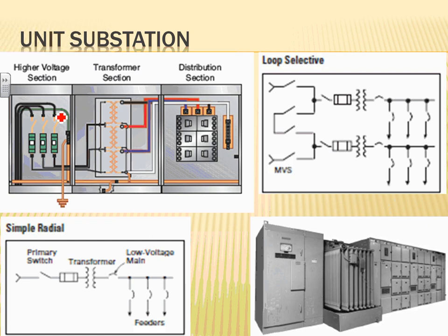Unit substation, I thought I'd just show you a lineup of a unit substation. We use these a lot. So here's your 13.8 coming in here. This is, let's just say, 2.5 MVA, and from this side will typically be the 480/277 system, very typical. I'm sorry, 277, believe it or not, here 277. We've also done a 208/120 substation in hospitals, 208/120 substation.